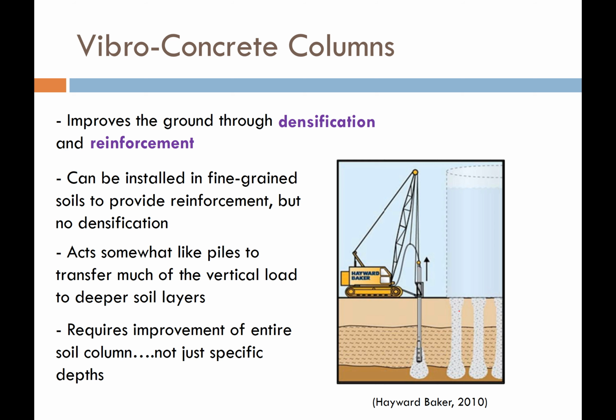Also, because these columns are now comprised of grout or concrete, which is a material that is very strong in compaction, these columns can somewhat act like piles, transferring a lot of the load from our structure up here above down to soil layers that are deeper down. Now that can be a good thing and it can be a bad thing.